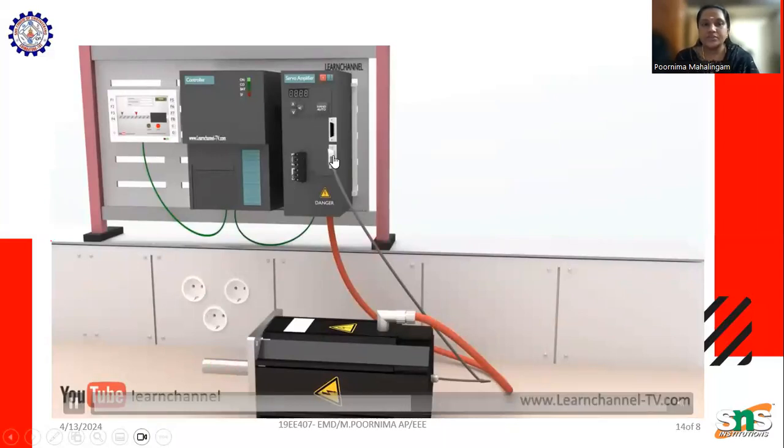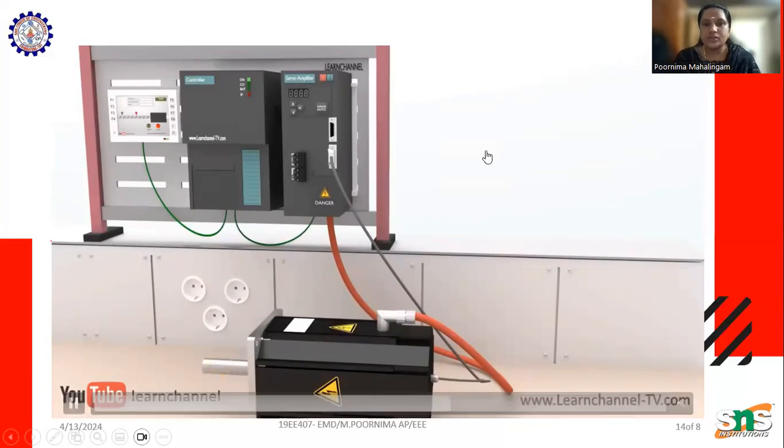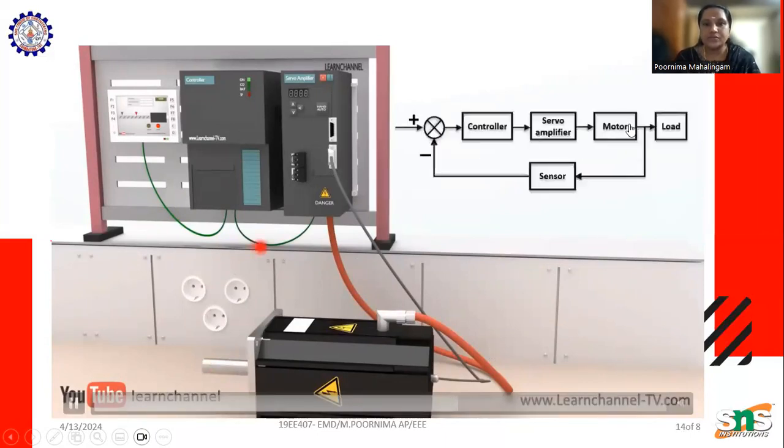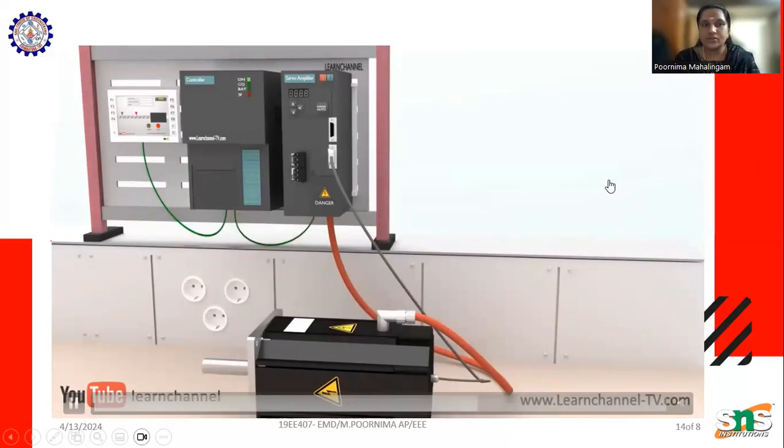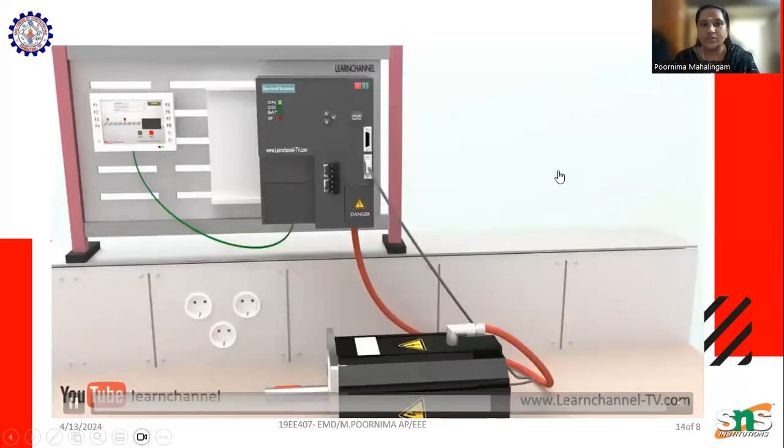The job of the servo controller, also named as the motion controller, is to close the feedback loop. The system does this by constantly interchanging data with the servo amplifier. You can see the motor parameters like torque, speed, or position can be adjusted immediately, so the sensor is giving feedback. You can see this is a closed loop control. Some manufacturers offer modules which combine the controller and the amplifier. You have fewer parts, fewer connections, and a smaller footprint. So combining both.